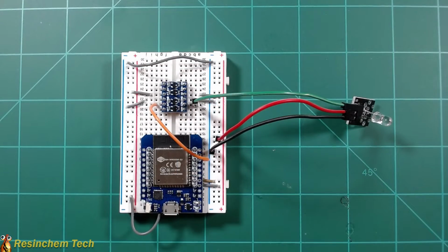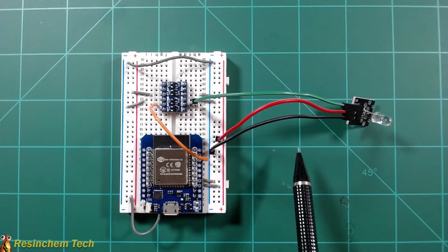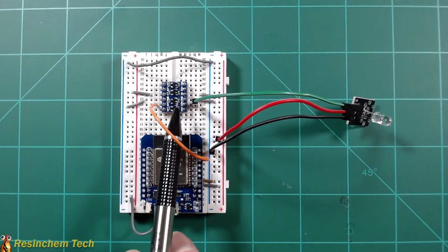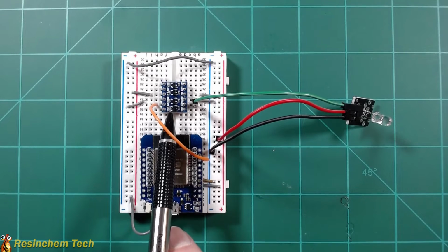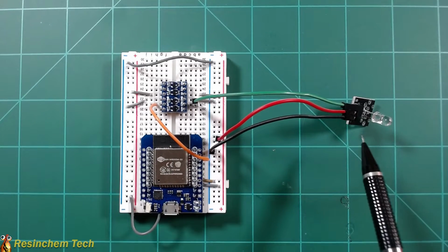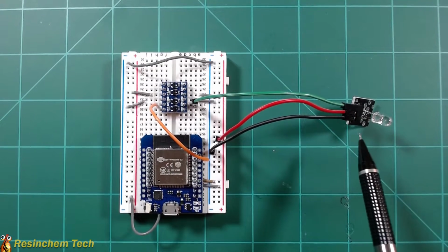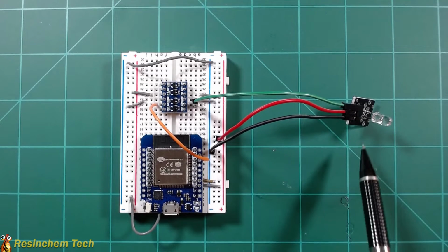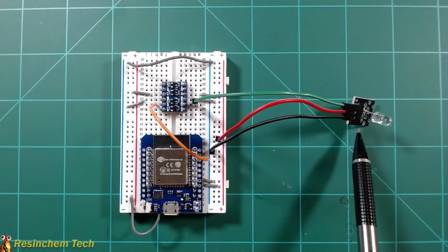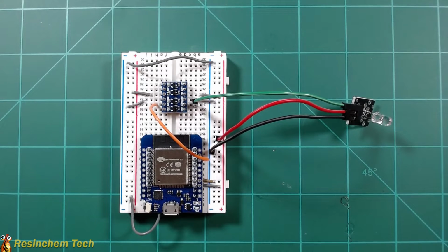This is the final breadboard version using the ESP32 and the other GPIO pin, and this all seems to be working pretty well in my particular case. Again, I am running the signal through a logic level shifter. I don't know if that's really necessary or whether it makes any difference, but it isn't hurting anything. And I am getting anywhere between 6 and 8 foot range off of this. It might even be further, but that is coming at about a 45-degree angle instead of directly in front of the air conditioner, and it still seems to work fine.